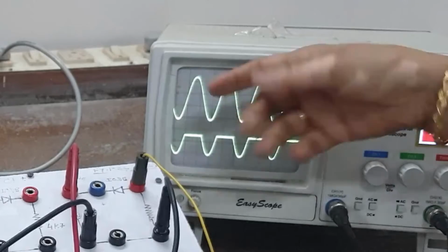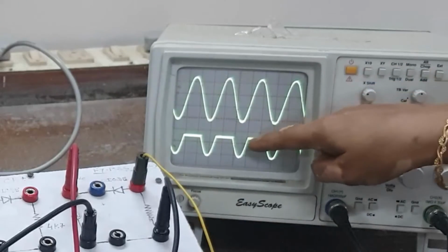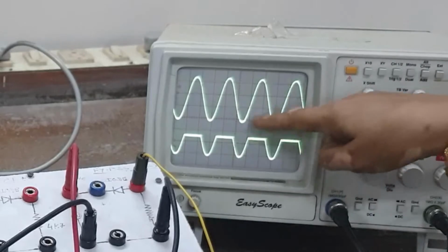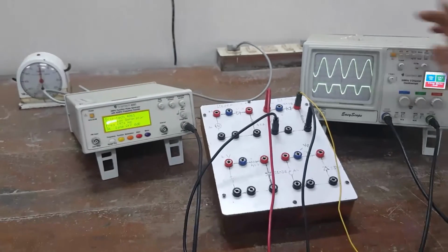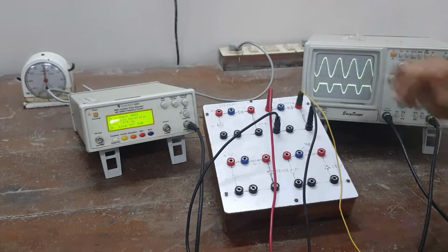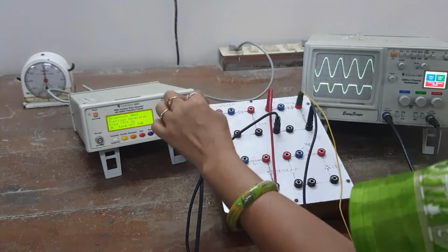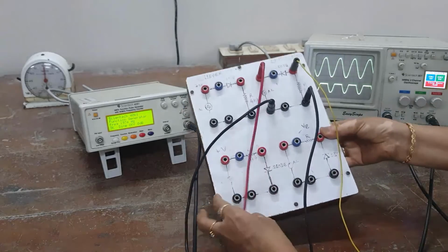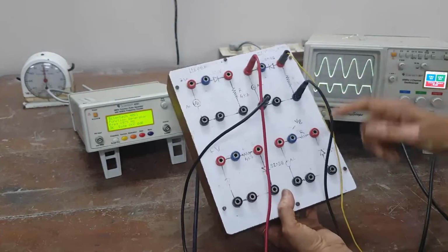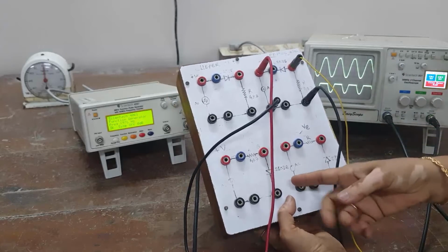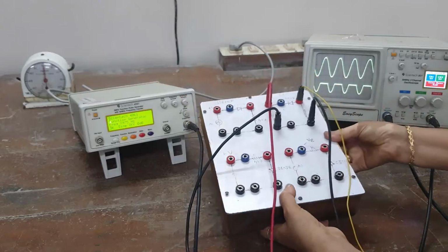So, the same principle you can apply here. During positive half cycle, the diode is not conducting and we are not getting any output. That is, the positive part is clipped off, that is, it is a positive clipper. First one was negative clipper. That is, the diode is connected in series. In the lower portion you can see the diode is connected in parallel, that is shunt. It is in shunt.